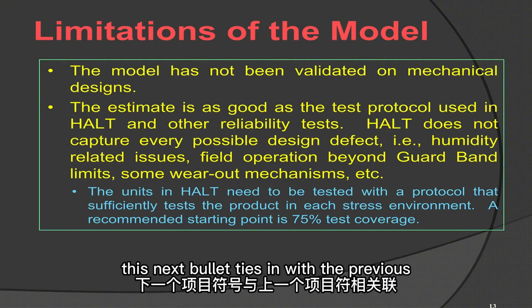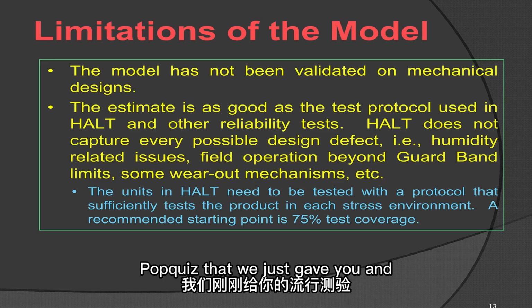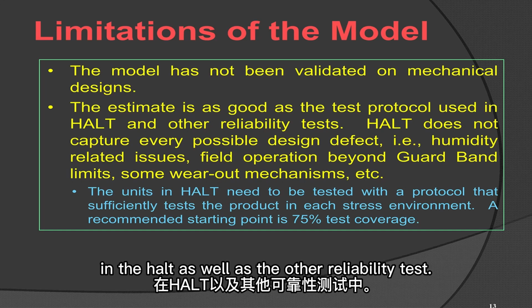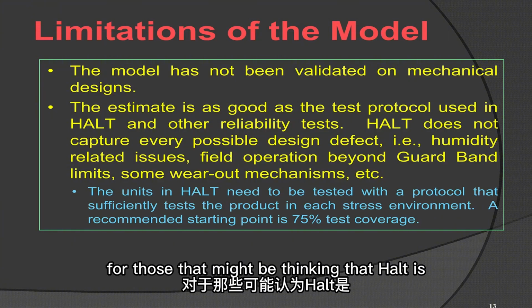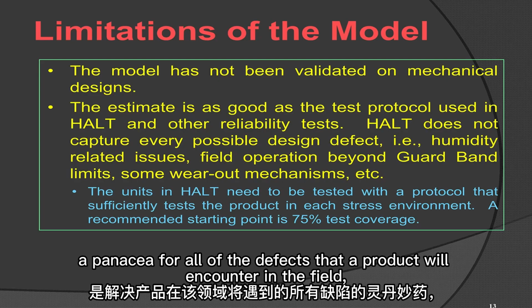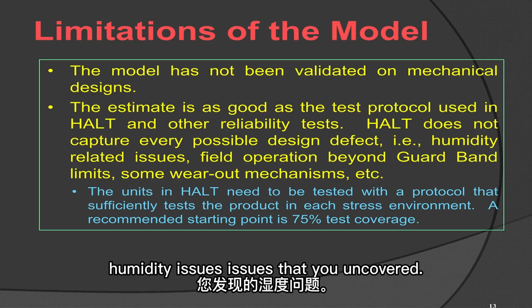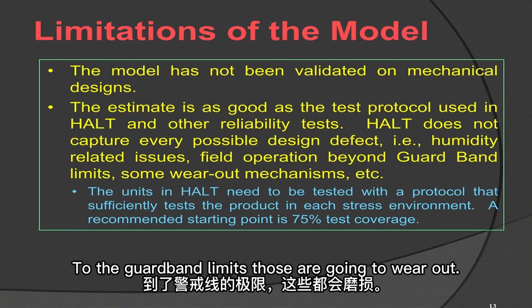And again, this next bullet ties in with the previous pop quiz that we just gave you, and we want to make sure that the test protocol is as good as the one used in the HALT, as well as the other reliability tests. So keep in mind also, for those that might be thinking that HALT is a panacea for all of the defects that a product will encounter in the field, there couldn't be anything farther from the truth, because, for instance, humidity issues, and issues that you uncovered but didn't push to the guard band limits, are going to wear out.